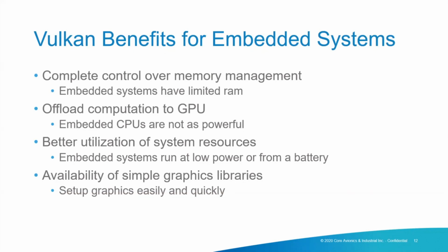So embedded systems are usually low power devices that potentially run on a battery. And if you can make better utilization of your system resources, parts of the device can be underclocked or have their power usage reduced or go into low power sleep modes, which means that they won't be running at peak power for the entire operation. And this leads to better battery life or running a cooler system, which is a requirement for a lot of embedded systems.